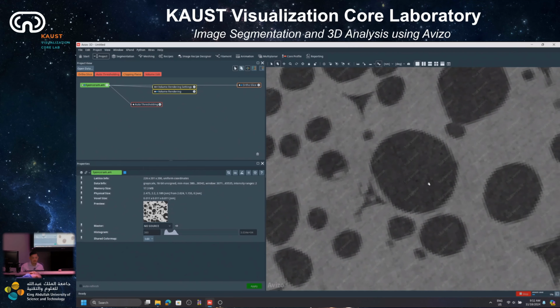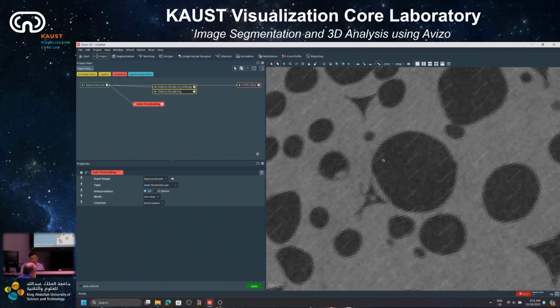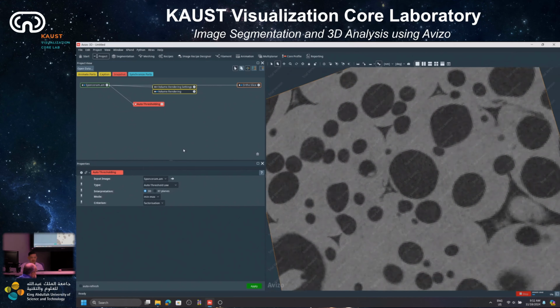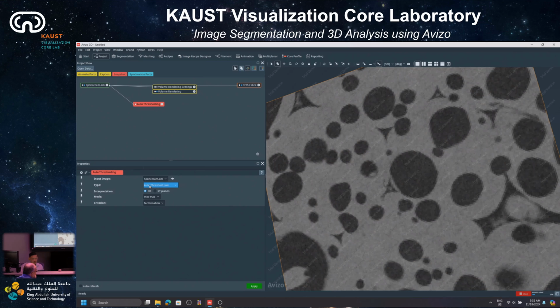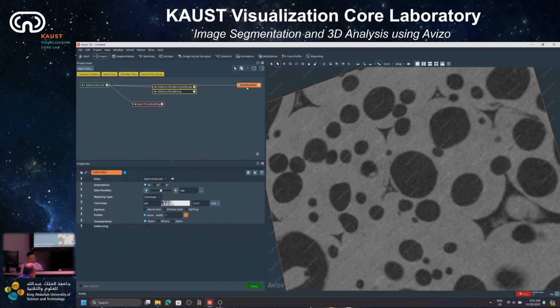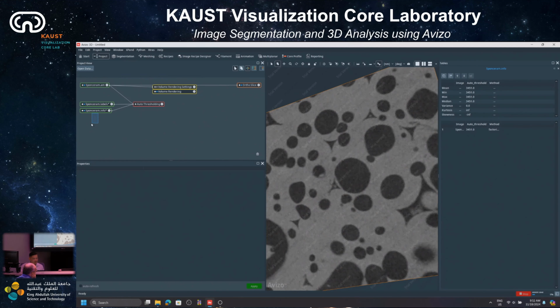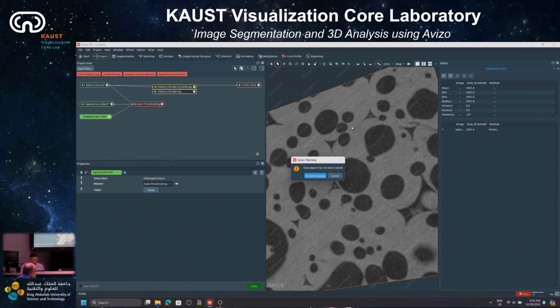So this auto thresholding module just automatically detects the pixels that have intensity in a higher range or in a lower range. So you can just select. If you select auto threshold low, you just threshold or create a mask over only the darker pixels. But if you select auto threshold high, you can create the bright material. But you can do both. I can also give you an alternative as well. So if I quickly select auto threshold low and click apply, then you always get an info file, delete it if you don't need it.